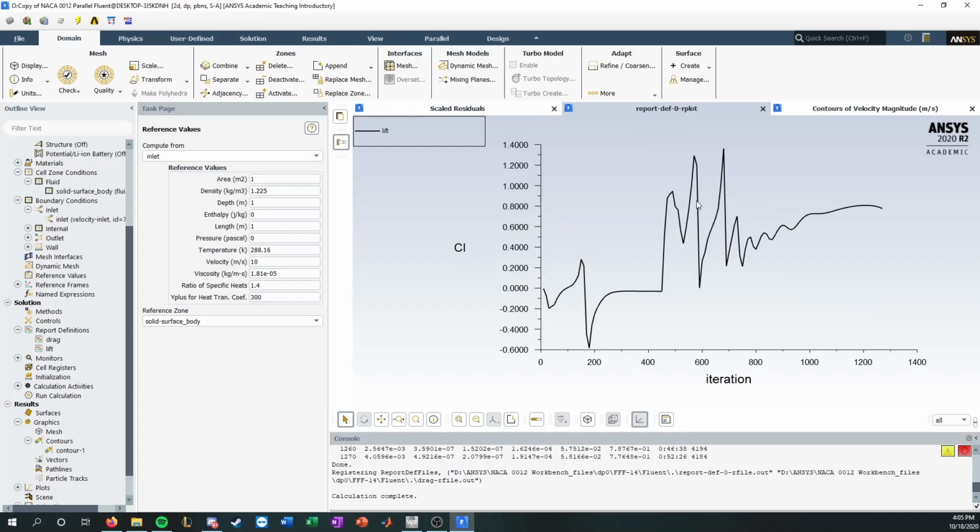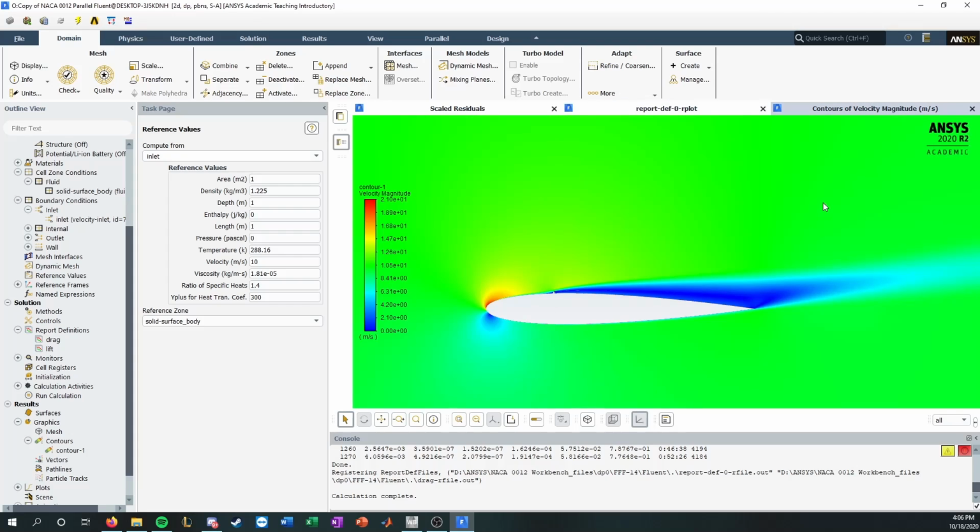And so this is stereotypical behavior of where you're trying to find a steady state solution to something transient. So separation will create a wake and vortices that will go after. And that behavior is transient. And so you're trying to take an average, which is what we're trying to do, take a steady state solution of something that's heavily transient. And so you get that type of behavior.